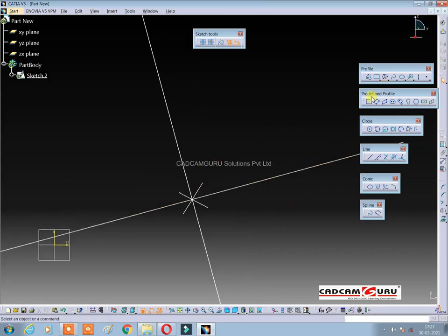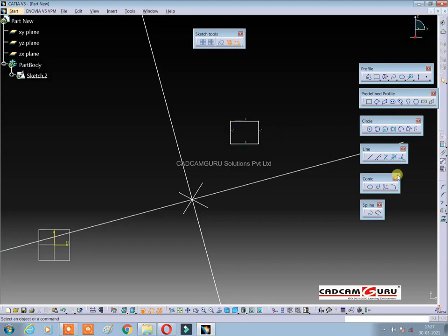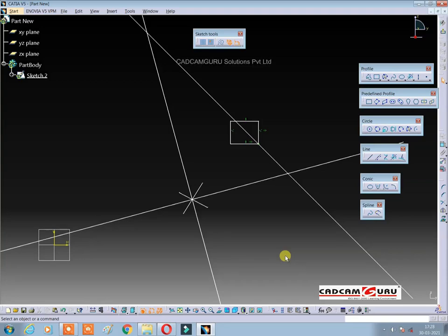So you can use a rectangle as well to create a bisecting line. I will show you. So select this bisecting line tool and you can select these two lines. It will create the bisecting line. This needs only the corner created by the two lines. Then it will create the line passing through that intersection point, and you will get the bisecting line. I hope you understood how to create a bisecting line.